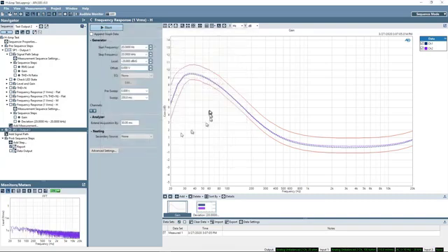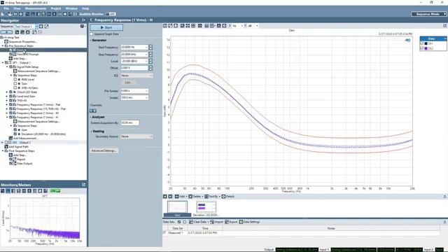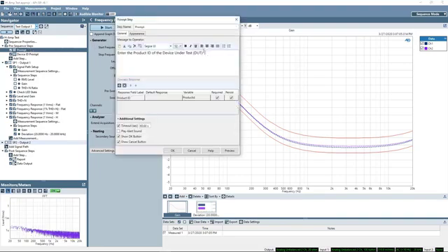Let's close this and look at some of the other properties that we have here. If I look at the sequence test output 1, you can see the collection of check boxes is different than it is for test output 2. If we go back to test output 1 and drill in a little bit, let's first look at some of the pre-sequence settings. Here we have the prompt. If we double click on this, we can open it and edit it or look at it. This is the prompt to enter the product ID of the device under test.